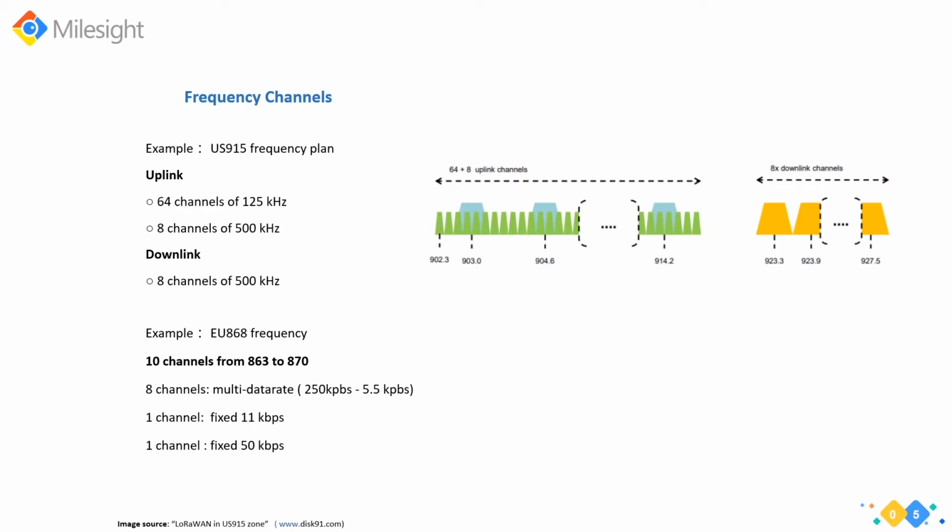Well, the answer is no, because LoRaWAN gateways are limited. They only support 8 or 16 channels for simultaneous communication with sensor nodes. Besides the fixed channel quantity in the gateway, you have to respect the legal regulations, I mean the duty cycle and the dwell time.